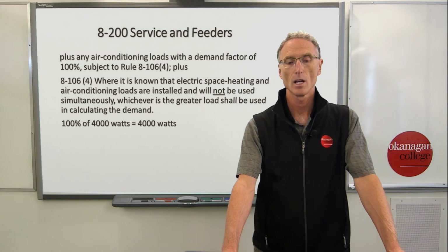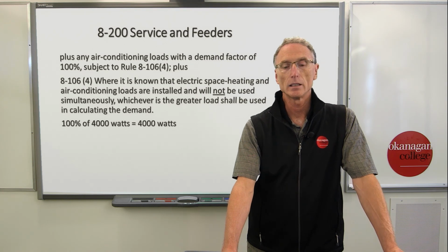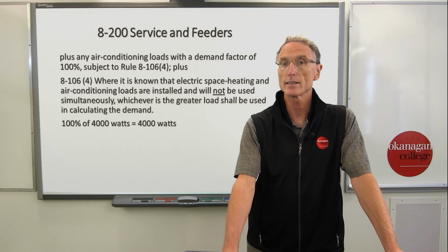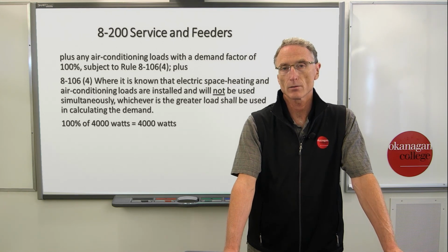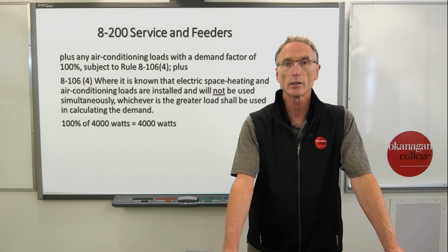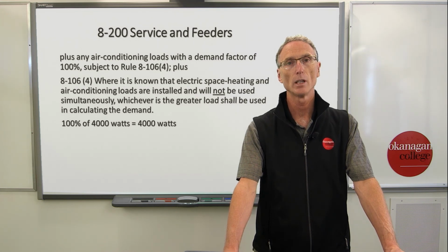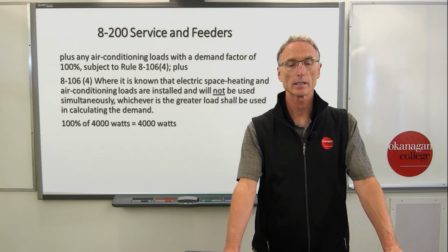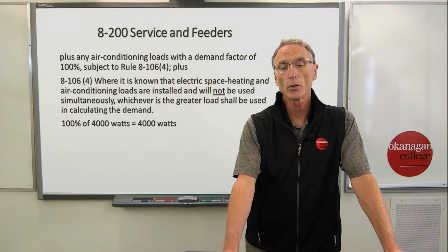That's quite an expense. But I have actually done that, wired the baseboard heating in conjunction with the AC, and one or the other will come on. And where this is logical is, if they're not connected together, you could have both loads on at the same time. Your air conditioning could be wanting to cool a room if it's hanging in the window, and the baseboard heat, if it's not interlocked, you could have both of them fighting each other.